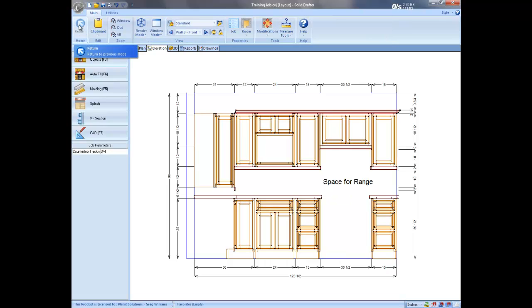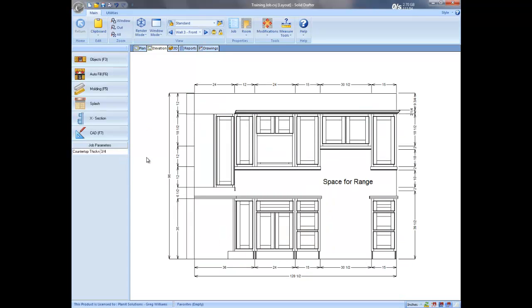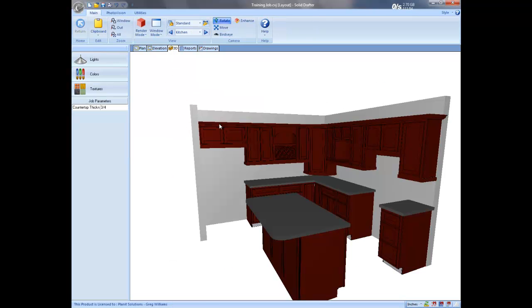Clicking the Return button escapes or turns off the CAD tool, and the text that I added will now be part of the view that is sent to drawings. Once again, right-click, choose To Drawings from the right-click menu, and that will re-render the view according to the layer settings. You may also send a view from 3D to the drawings part of the program.